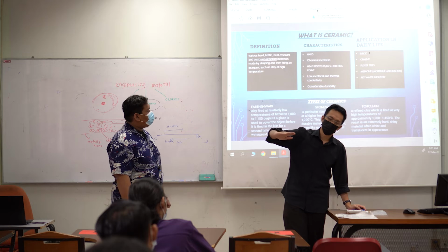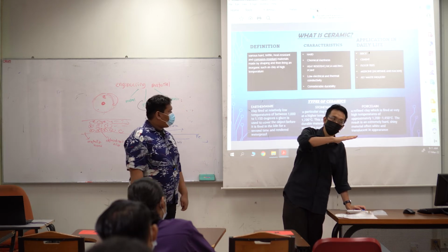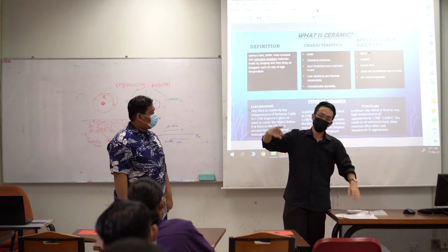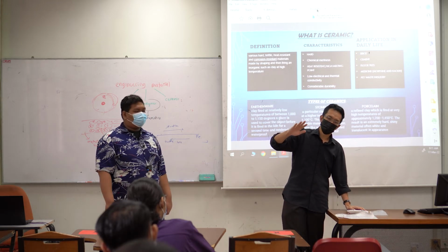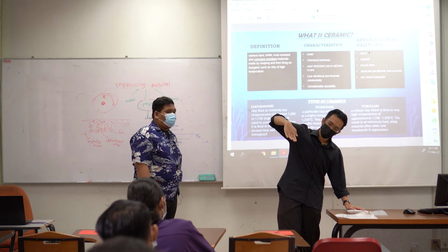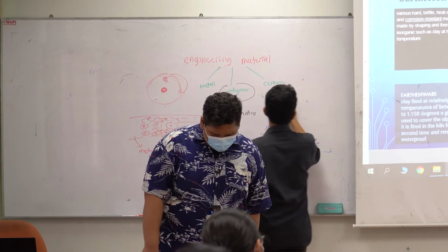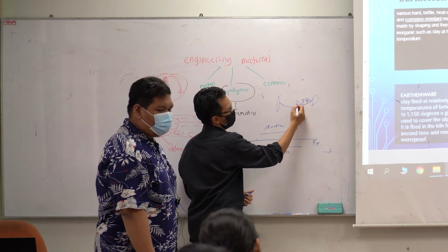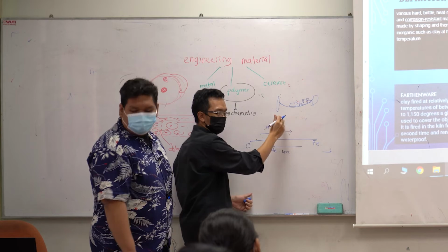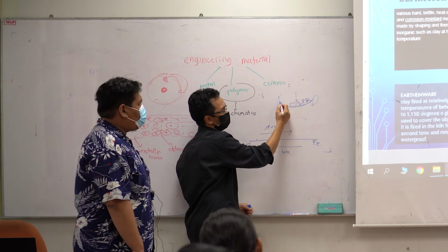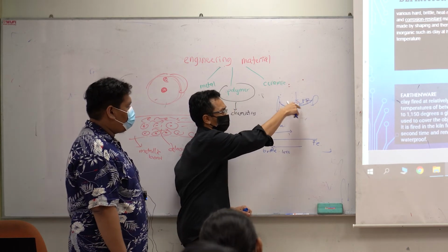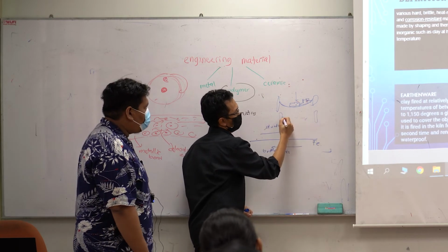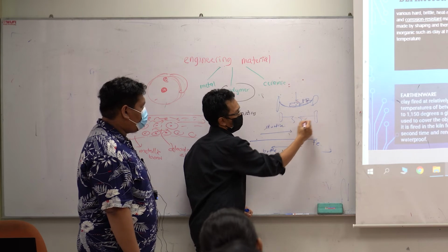This metal, people use it for the construction because you can see the warning. You see a car moving on the bridge, and you see that the bridge somehow dents a little bit. So at least people on the side see the bridge sort of like this. Somehow you can see the bridge dent when the car moves. If there is enough more weight on the bridge, then you can see the metal will show its ductile property. But if you use ceramic, then without any warning, it will just break like a concrete.